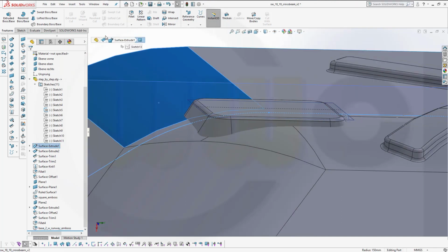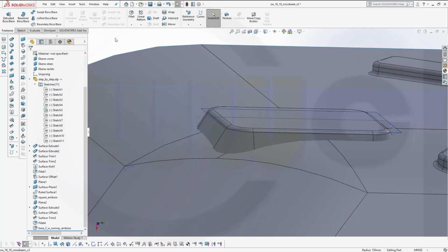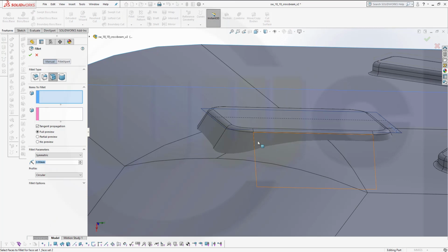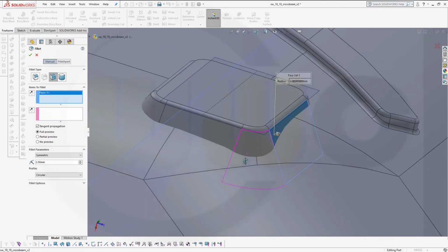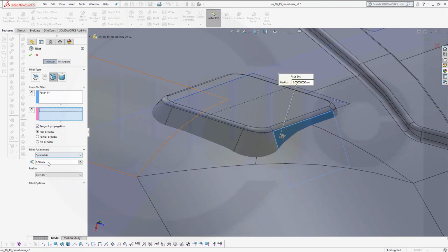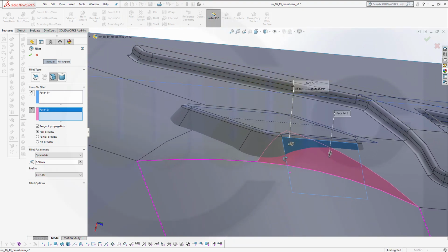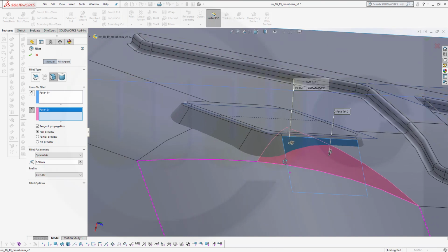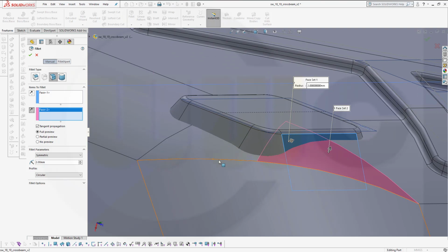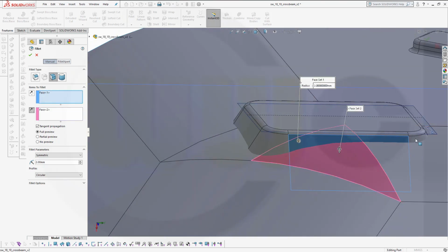Now let's go for another fillet. A fillet between this surface. Arrow should go to the outside, yes. And of course tangent propagation, 2 mm or 3 mm, and select this one, and the arrow should go up. So there's no preview, and it might not work, or I have to select some more. Let's try some more. Select here and there.